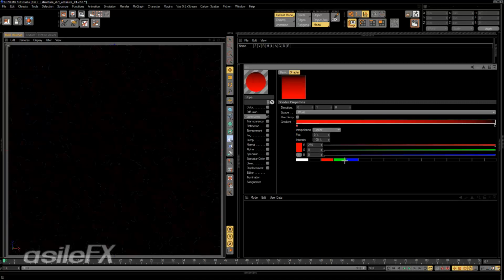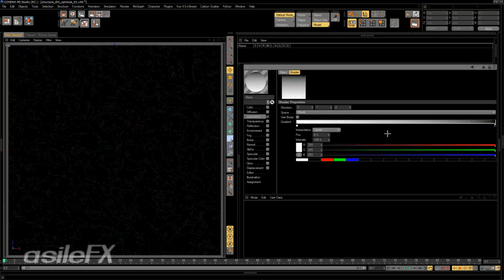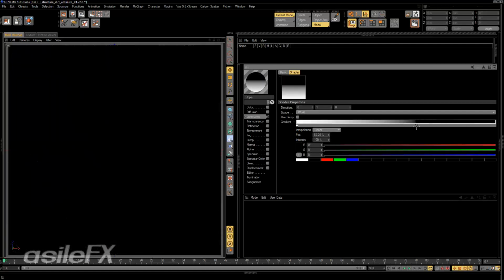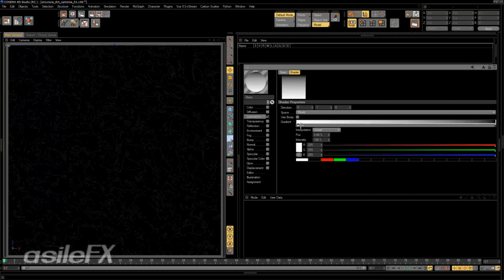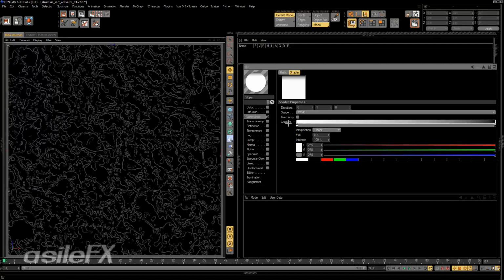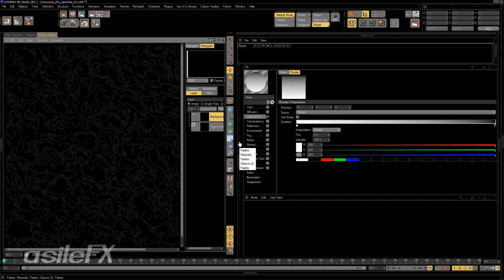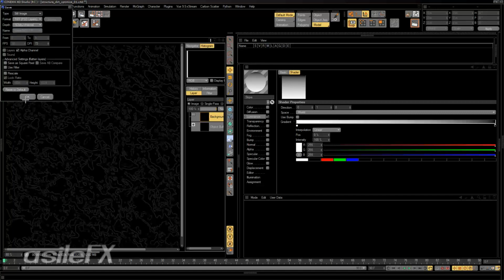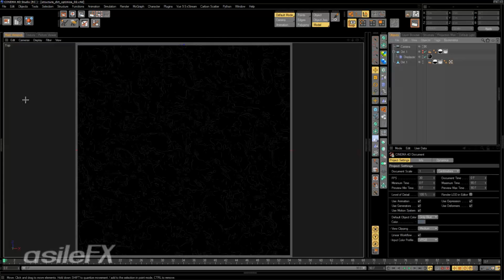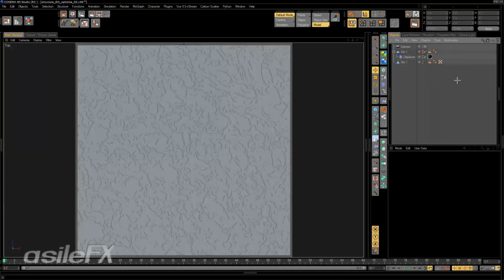We can set up a color if you want to assign it that way, or even a mixed amount throughout. And we could clip the range if you want to set it up ahead of time, but this should be good, just this gradient. So we go ahead and render that out. And now we've got something for slope. So those are really just the two materials I think I need. Go ahead and just remove those tags.